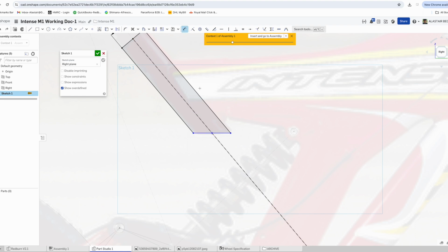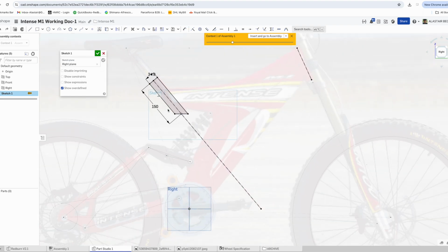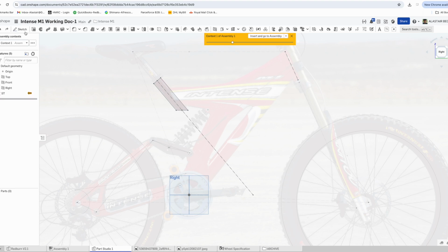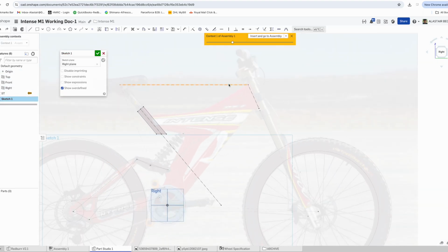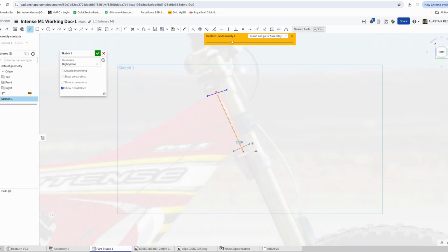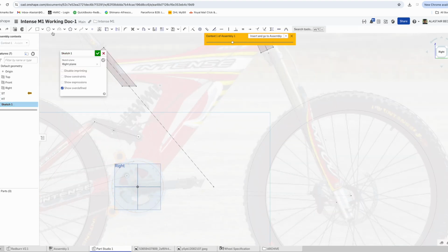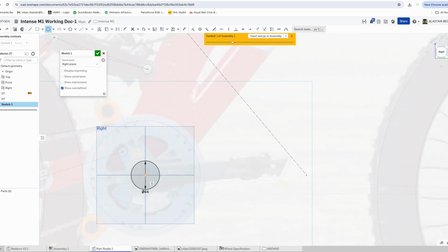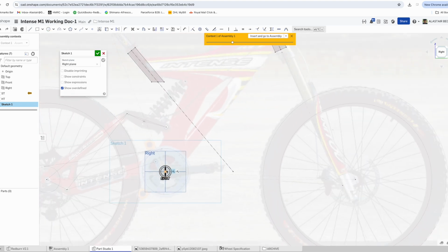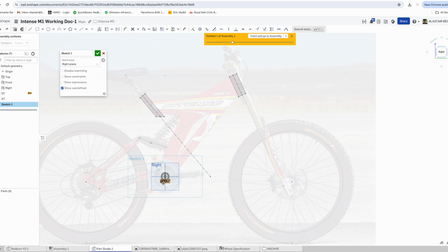Then we'll come back and tidy up a lot of dimensions afterwards at a later date if anything doesn't work or if there's no clearance on certain elements. So here, you can see the seat tube layout. We're going to work on the head tube layout now as well. Back then it was probably a 44mm press-in cup headset back in 2002, 2003. So we're just putting some basic dimensions in here. Again, just a straight tube. We can always come back and put some butting in there or some bearing tolerances and things at a later date. But for this, this is satisfactory. And again, BB shell, put the simple round tube stuff in first and then work from there.